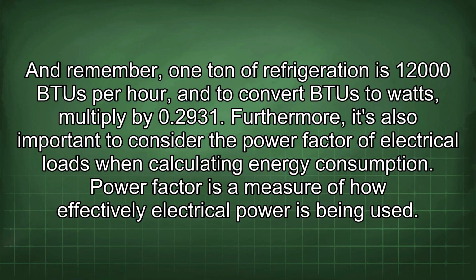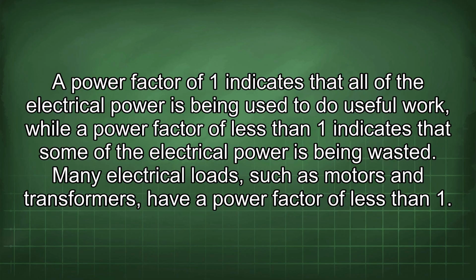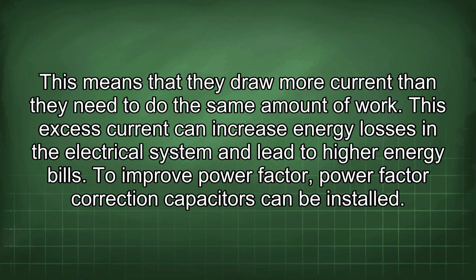Furthermore, it's also important to consider the power factor of electrical loads when calculating energy consumption. Power factor is a measure of how effectively electrical power is being used. A power factor of 1 indicates that all of the electrical power is being used to do useful work, while a power factor of less than 1 indicates that some of the electrical power is being wasted. Many electrical loads, such as motors and transformers, have a power factor of less than 1. This means that they draw more current than they need to do the same amount of work. This excess current can increase energy losses in the electrical system and lead to higher energy bills.